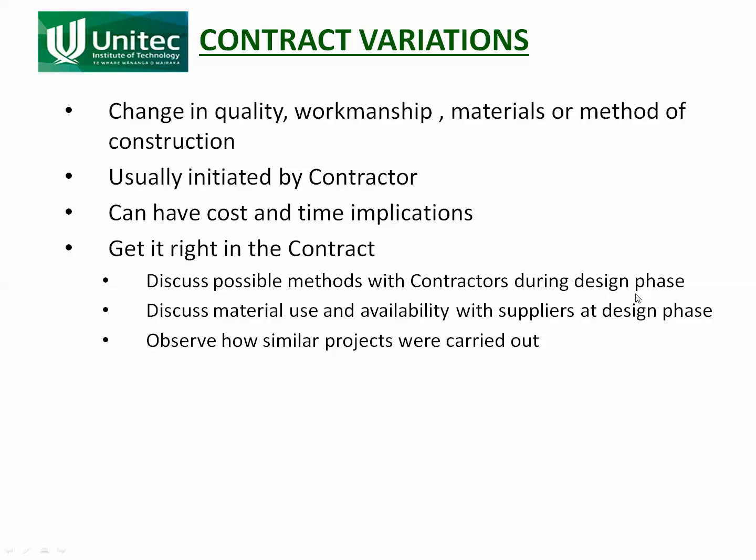So when you're doing the design, you'd ring up your contractor mates and say, oh, we've got this particular road that needs to be built on this particular soil. What sort of machines would you guys use? What sort of lime would you use to stabilize it? All those sorts of things, so that you're taking what the contractors would actually use on site and you're including that in your specification. Likewise,